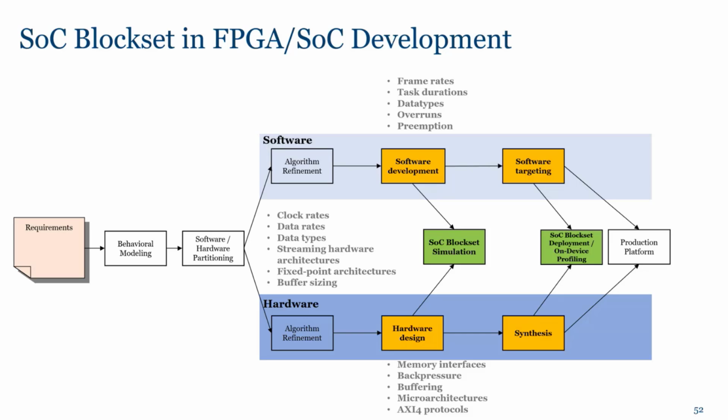They will use FPGA prototyping at the end, but in that case, SoC Blockset will provide an automated workflow to build complete hardware and software applications and deploy them on the FPGA and SoC boards. Ultimately, what we are trying to do is create a virtual platform and integrate the production platform, which is the custom FPGA board. We are creating a virtual platform that will combine all the effects that both of these partitions have on each other, but we will also see the effect that other parts have on the software and on the hardware parts.